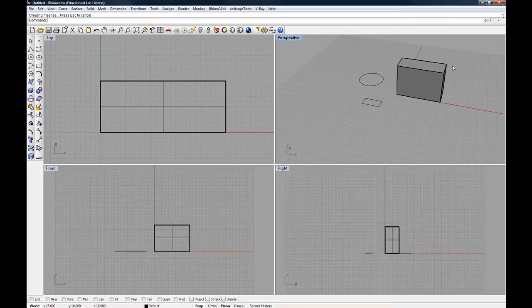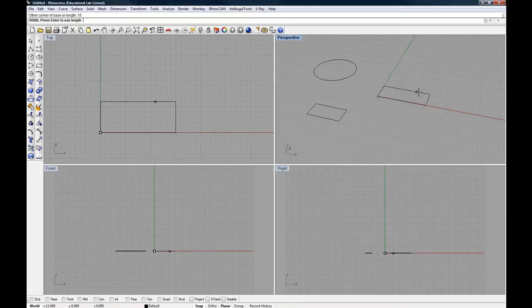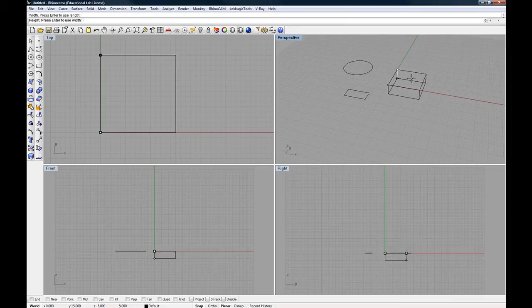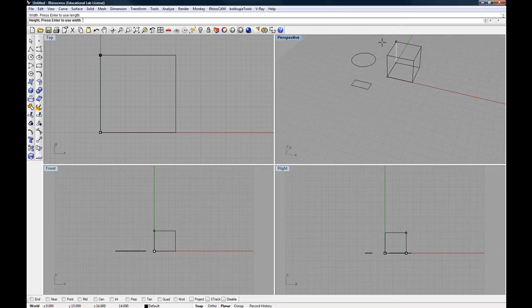Another easy way to create a cube in this case, if I wanted to use the same value, for instance, I'm going to rerun that command and start it at 0. So I'm typing 0 to start it at the origin. Let's say that I want to create something that's 15 by 15 by 20. Well, rather than counting out my units, I'm simply going to type 15 for the first dimension, and that sets the length going across. I'm going to just hit enter again. We'll use that same unit for the second input as well. And you can do this for a rectangular tool as well, for just a two-dimensional rectangle. And now I can specify my height, again, either just dynamically, or I could type it in. In this case, I'm going to just hit enter a third time, and it will use that same dimension for the height as well.